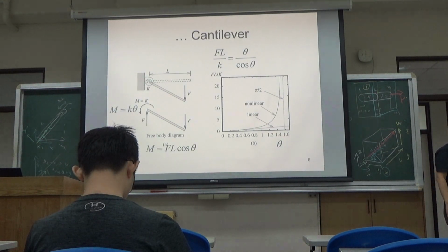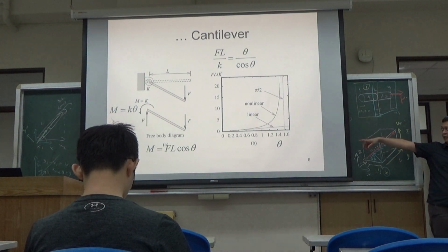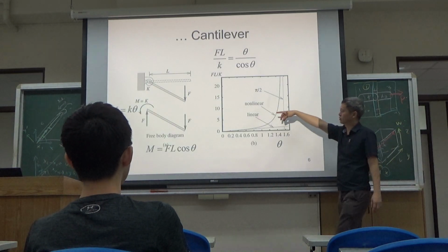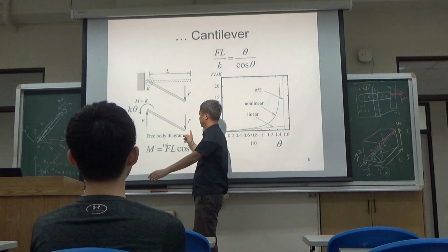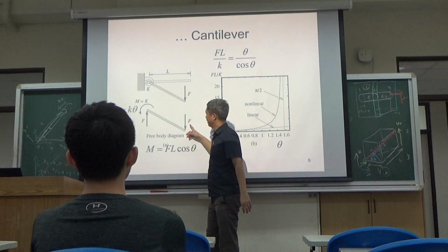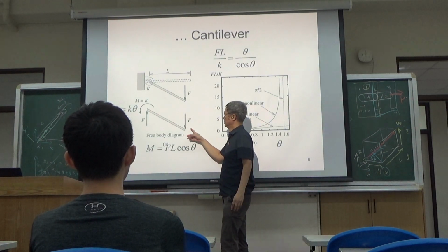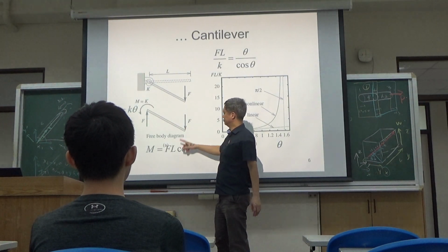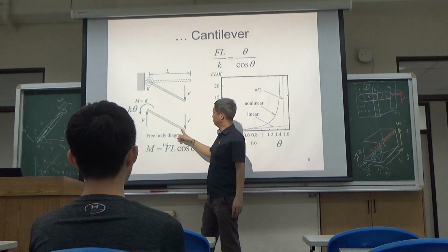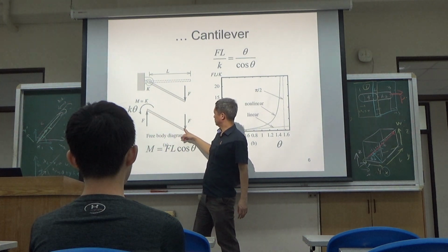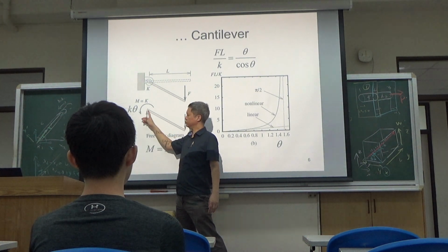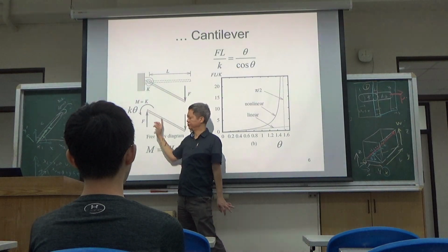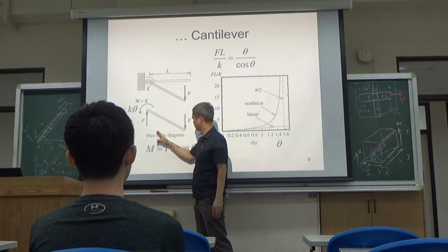And then when you apply the force on the door knob, if you apply that force in constant direction, you can find that as the door opens, the external moment reduces. Why? Because the moment arm between the applied force and the door hinge is shortened.